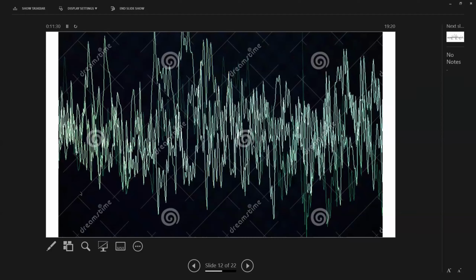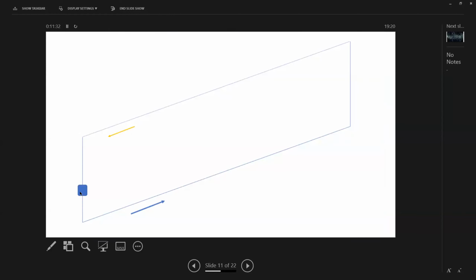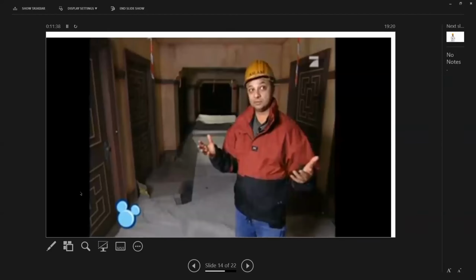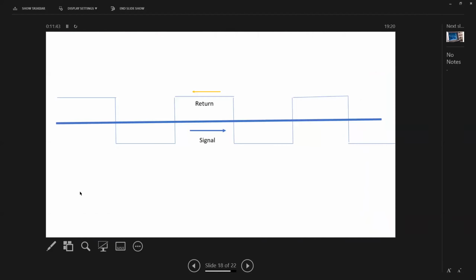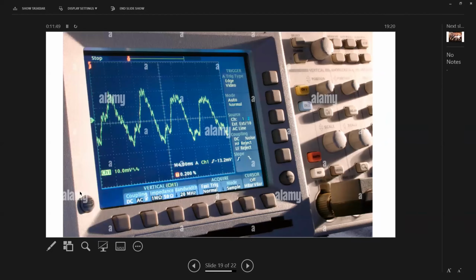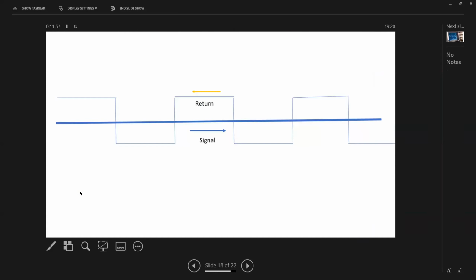Okay, well, obviously what these guys had done was built one of the world's biggest loop antennas, and it was going to pick up everything in the surrounding territory. So when we finally got a return path corrected and taped down on the floor as a demonstration run and took a look at what the scope gave us, okay, now this is stuff we can live with. That's reasonable. So that solved the problem.